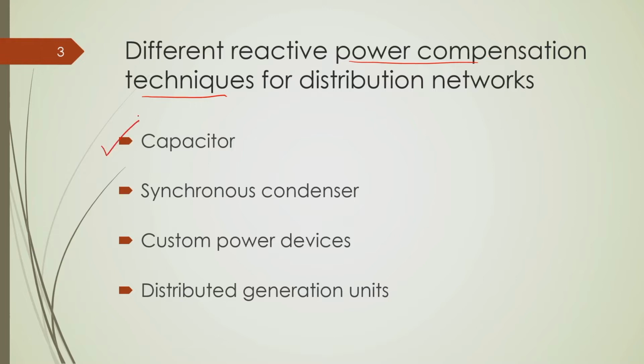One is the capacitor. As you know, a capacitor is a source of reactive power. Why do we call it a source of reactive power? Because most of our loads are inductive, and inductive loads also exchange some reactive power, and a capacitor also exchanges reactive power, and their exchange occurs just opposite to each other.